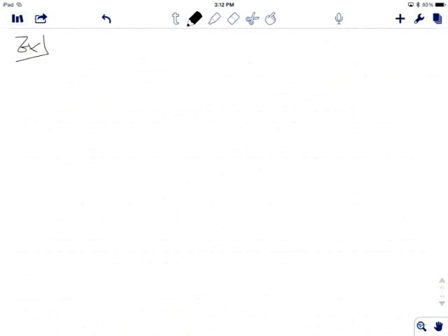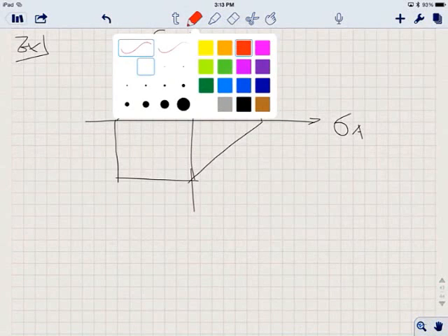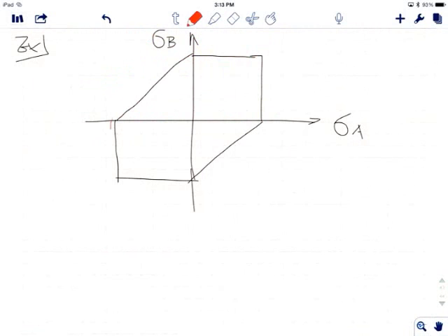Examples, finally. First of all, let me do a quick review of what we learned in the past week. Everything we learned in the past week can be summarized in this plot. You have two-dimensional loadings, and two different failure criteria to assess the failure of the material or system: maximum shear stress and distortion energy.